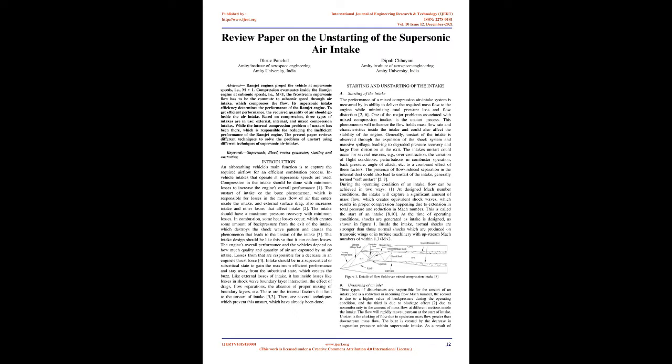The intake should have a maximum pressure recovery with minimum losses. 2. In combustion, some heat losses occur, which creates some amount of back pressure from the exit of the intake, which destroys the shock wave pattern and causes the phenomenon that leads to the unstart of the intake. 3. The intake design should be such that it can endure losses.